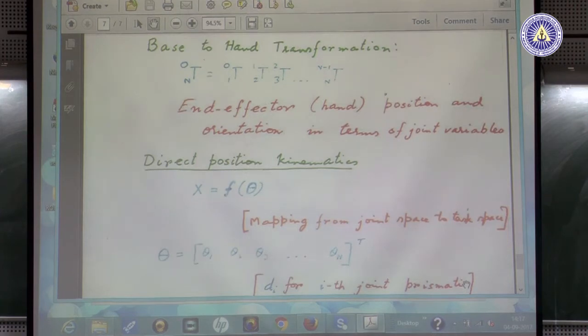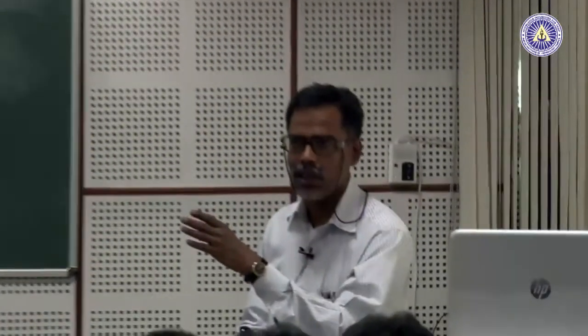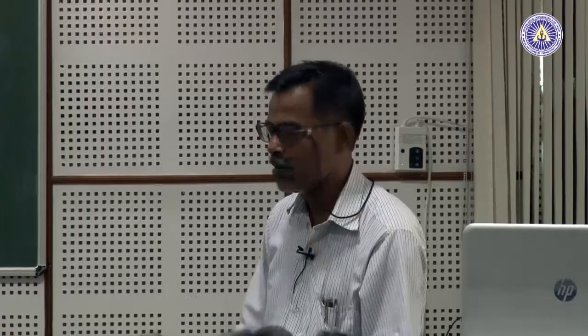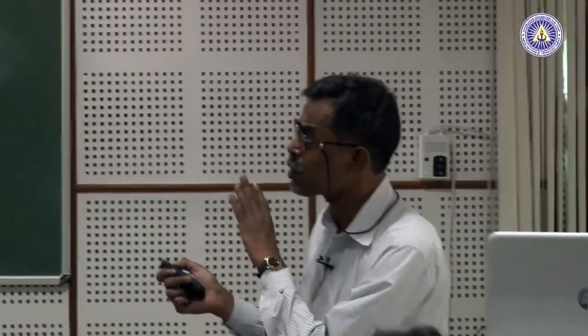So, for theta 3, the quantity tan theta 3 by 2 you define as t, and in that t you can derive a 16 degree polynomial, a huge, long, very monstrous looking polynomial equation. By the solution of that 16 degree polynomial equation you can find 16 values of theta 3, and for every value of theta 3 you can accordingly get the values of the other unknowns.